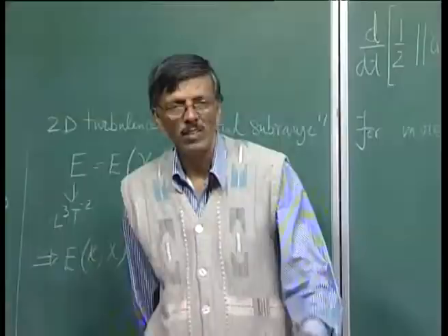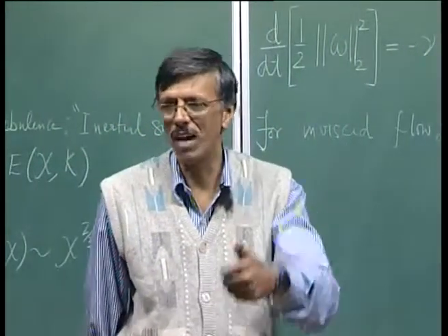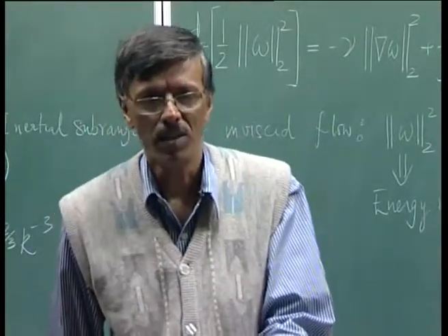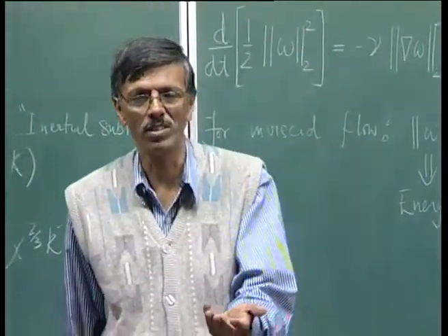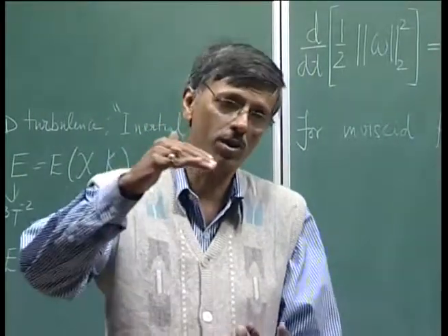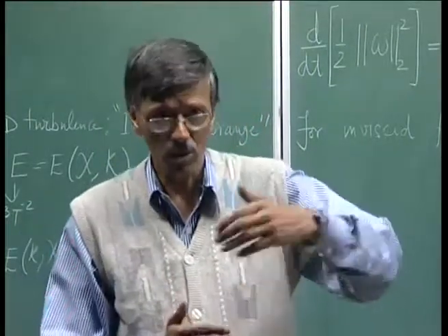Sir, for the mixed convection problem, how do we exactly arrive at assisting and non-assisting flow? I mean, with the sign of K. Well, with the help of your direction of the gravity. See, there the body force was due to the buoyancy term. That's your Boussinesq approximation. So, if the gravity assists the convection, how would the convection go from a hot surface?